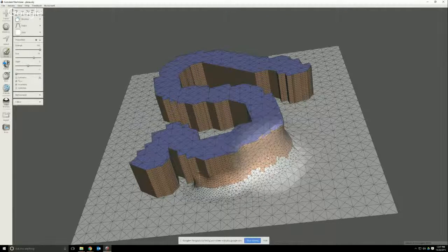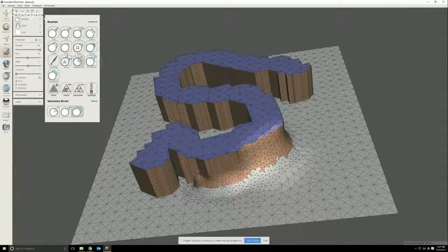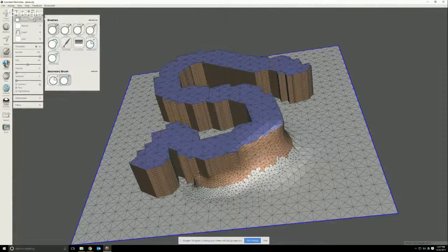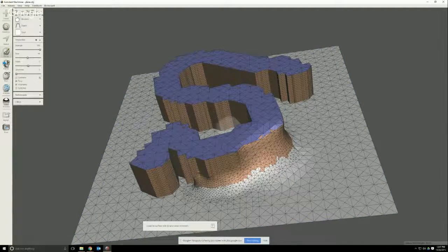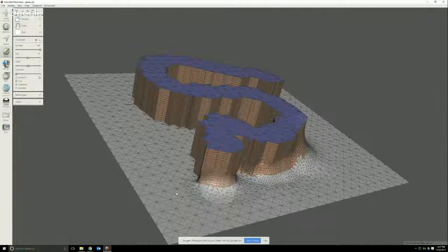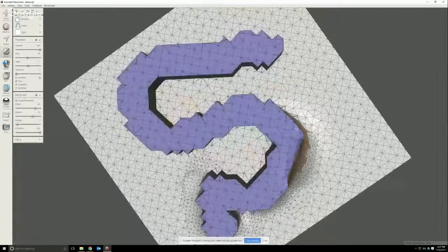I generally try to use that because it's a good smoothing tool, whereas the other smoothing tools like bubble and shrink really do change the mesh quite a bit. You can also go into surface. The smoothing here also does it, but I generally try to start with the robust smooth. So what I'm going to do in here is refinement, do a bit of reduction, and just very, very quickly go around.